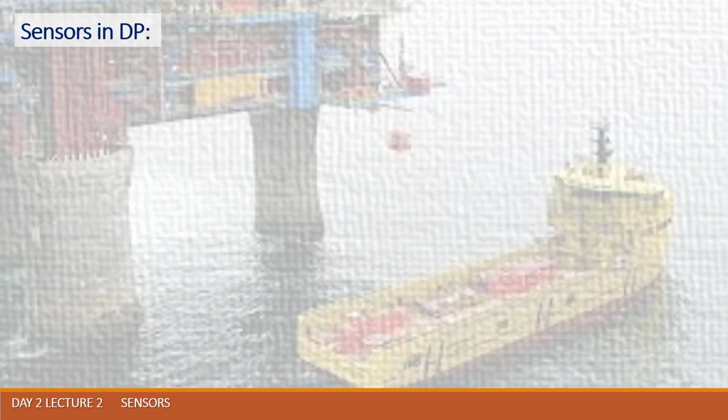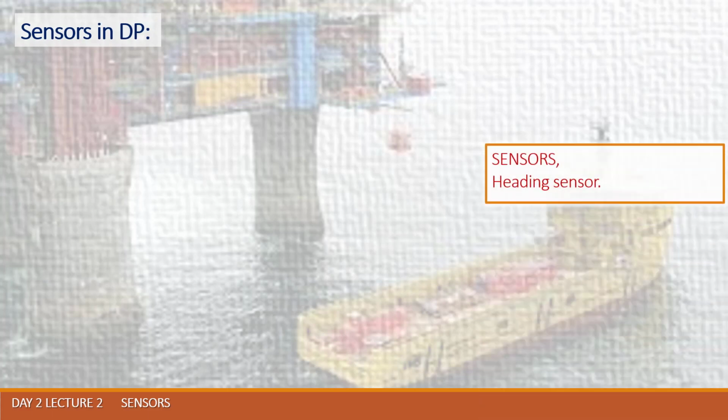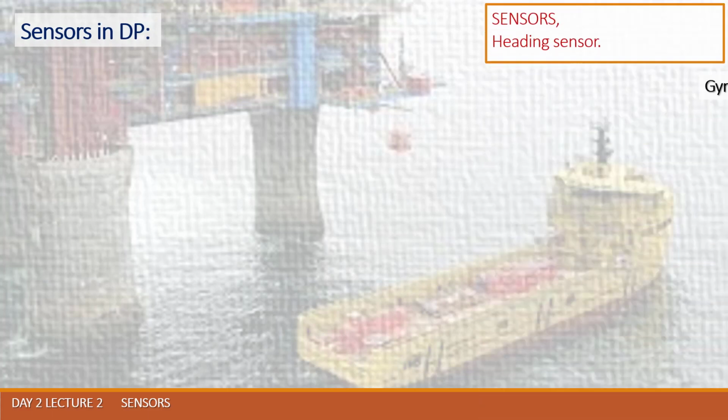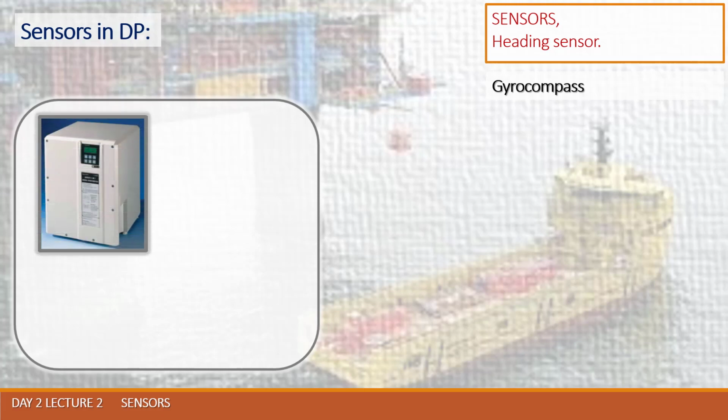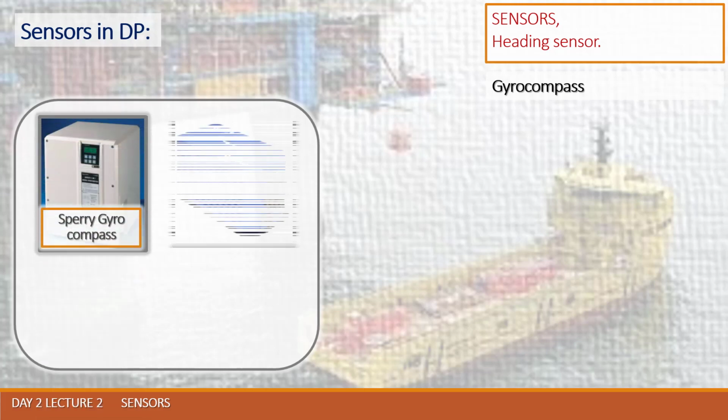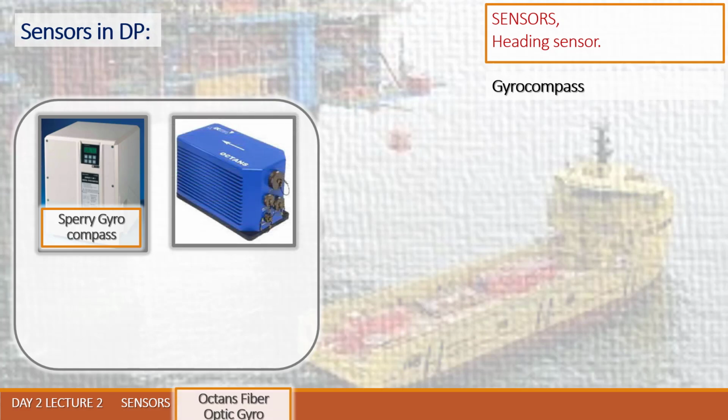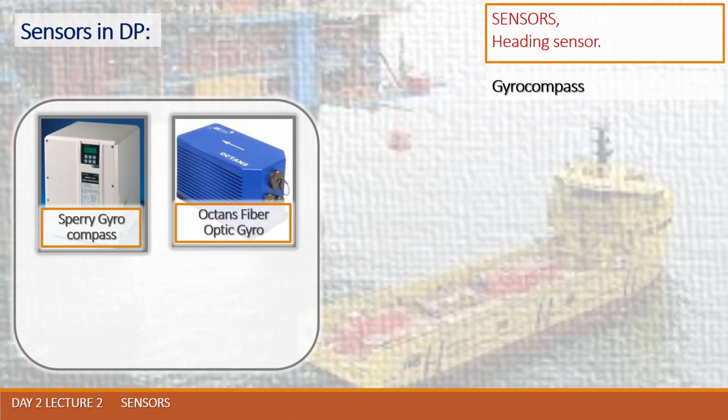The gyro compass finds north by using an electrically powered fast spinning wheel and friction forces in order to exploit the rotation of the Earth. The laser gyro or fiber optic gyro use interference of laser light within a bulk optic ring or a coil of fiber optic cable to detect changes in the orientation and spin and thus to find north.